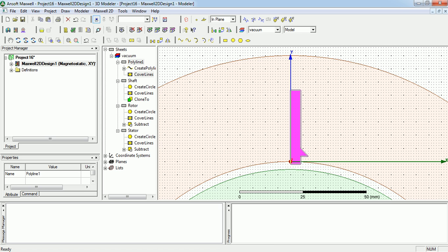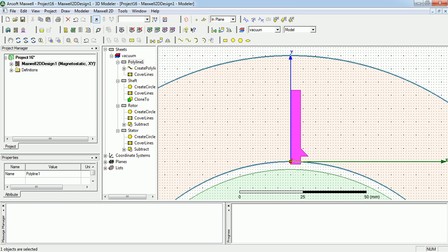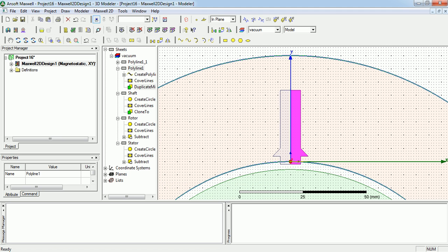Once you have the half slot, right click on it, click on the half slot, then go for the mirroring option. This is the mirroring option, mirror duplicate, click here, and we have the mirrored option. Click on the first portion, plus control, click on the second portion and combine, unite. We have the boolean operation, so we have one single, complete slot here.